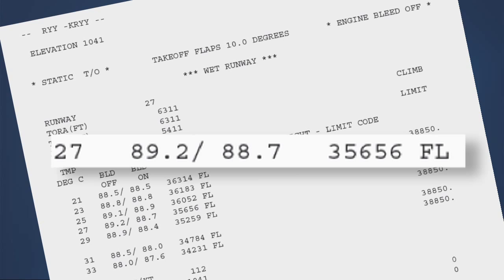If the crew relies on the flight management system to compute their required takeoff field length, which in this example is 6,273 feet, they may not be warned that this value has exceeded one of the runway's declared distances. The 6,273-foot takeoff field length required exceeds the runway's accelerate stop distance available of 5,374 feet. The flight management system will provide no warning message of this exceedance.